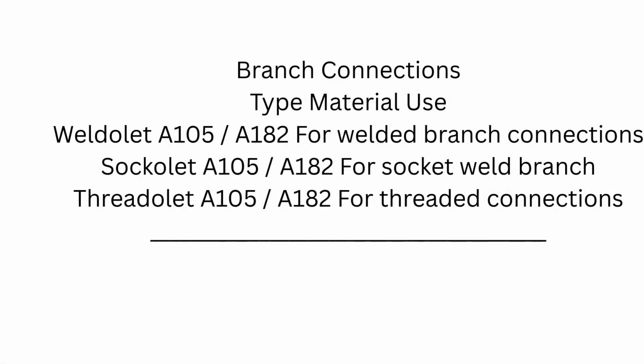Branch connections, material used. Weldolet A105, A182 for welded branch connections. Sockolet A105, A182 for socket weld branch. Threadolet A105, A182 for threaded connections.